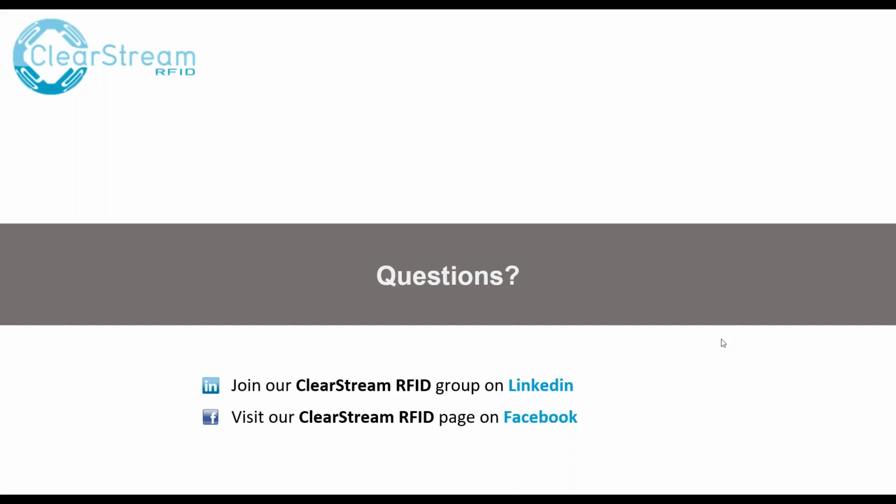So those quiet tags are now quiet, and they're letting the reader read more tags and hence do that hard-to-tag inventory and try to complete those tag readings as well. And this gets combined with the search mode, single target and dual target. Single means that if you read a tag once, it'll only be read once, but you can do that a couple of times. And dual means you're constantly reading tags.